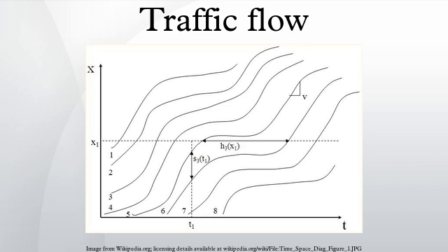Components of the kinematic wave model of traffic flow theory. The kinematic wave model of traffic flow theory is the simplest dynamic traffic flow model that reproduces the propagation of traffic waves. It is made up of three components: the fundamental diagram, the conservation equation, and initial conditions. The law of conservation is the fundamental law governing the kinematic wave model.